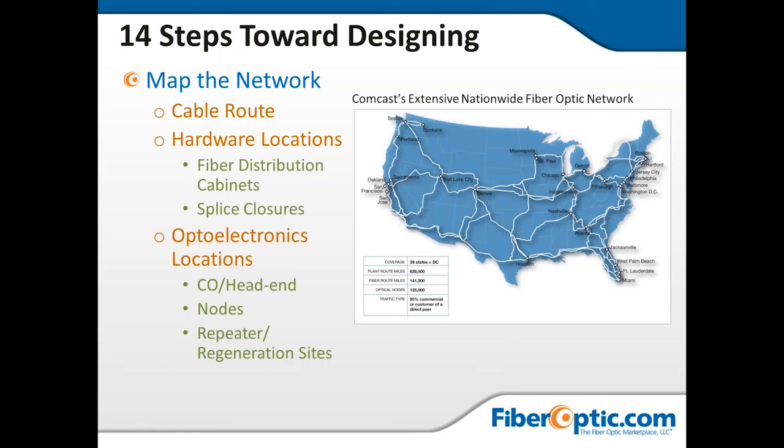Make sure it's accessible. Make sure you can get to it. Make sure it's not in the middle of an intersection in a manhole with two 6-lane highways crossing. Move it around the corner and up onto the side of the road. Make it easy to get to with minimal impact on traffic, because if you have minimal impact on the idiots behind the wheels of vehicles, you will have safer technicians.